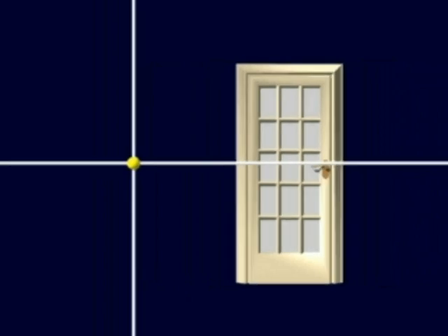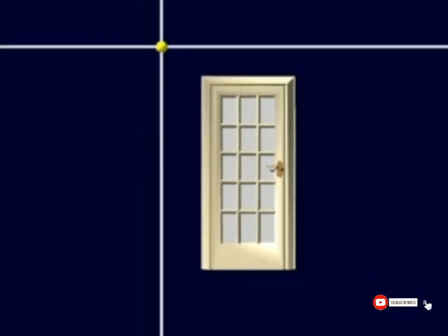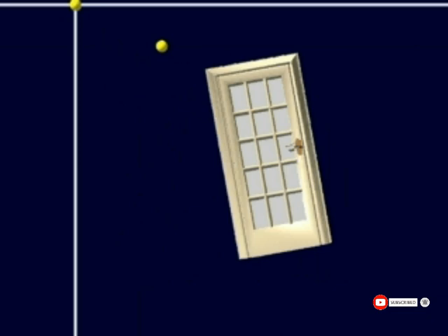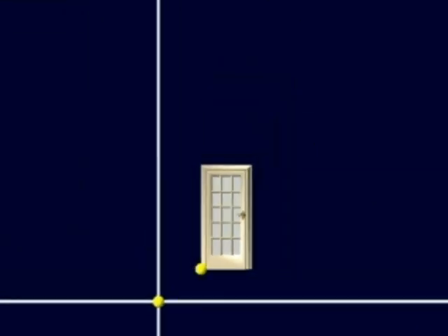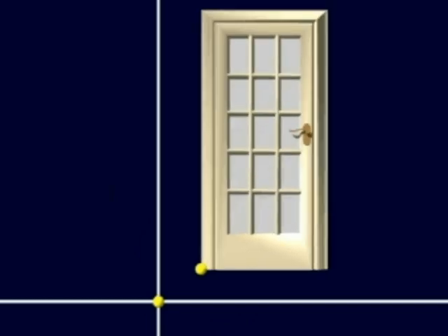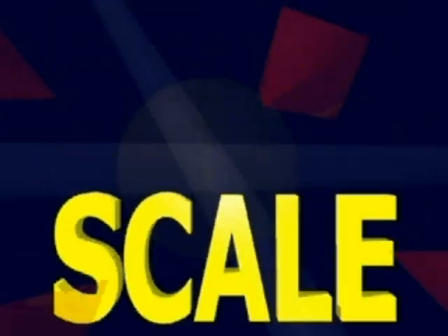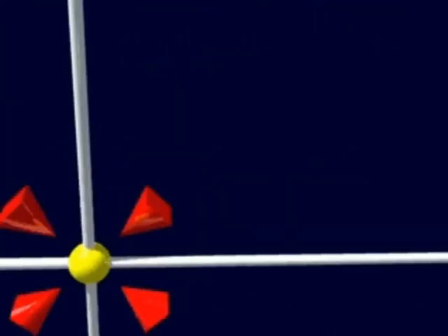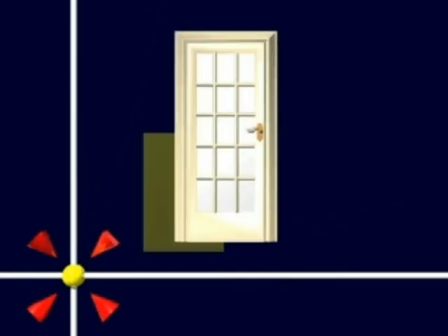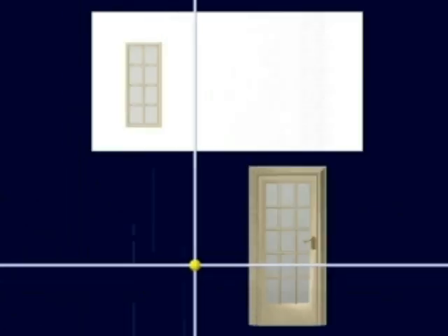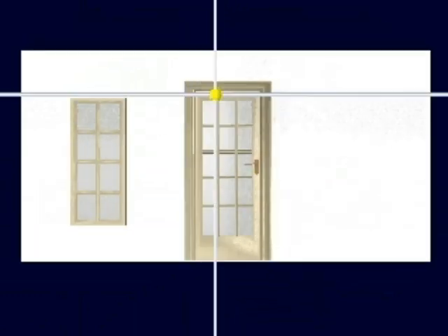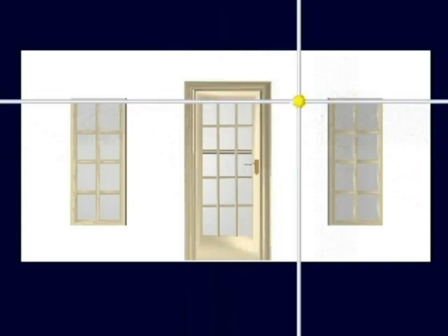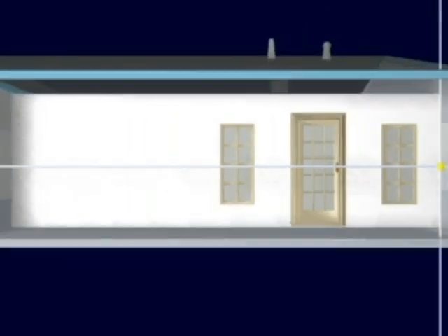If you rotate an object, the base point you specify determines the point about which the object spins. If you scale an object, the object scales inward or outward from the base point. Many editing operations require you to provide a base point, which serves to determine the final position or shape of the edited objects. Learning how to locate base points correctly lets you place one object at the center of another, mirror geometry to create a symmetrical part, or, for example, stretch a wall to change the location of a door.